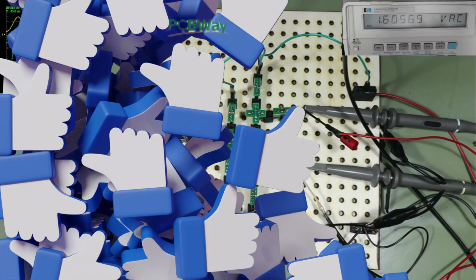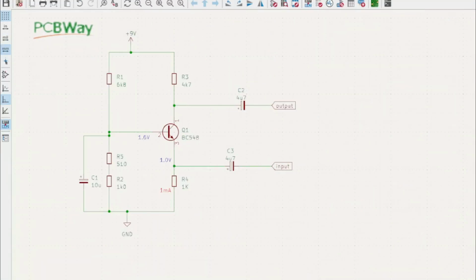calculated values. Now we need to talk about the AC characteristics of the amplifier, having just seen what we measured at 10 kilohertz. The frequency was set at 10 kilohertz as opposed to the normal 1K, as the input impedance is very low, and it's a small capacitor, so they together could be acting as a high pass filter and lowering the gain. So I've upped it to 10 kilohertz. We should be well away from the slope of that RC filter. So what is the gain, and is it the same as we measured it?